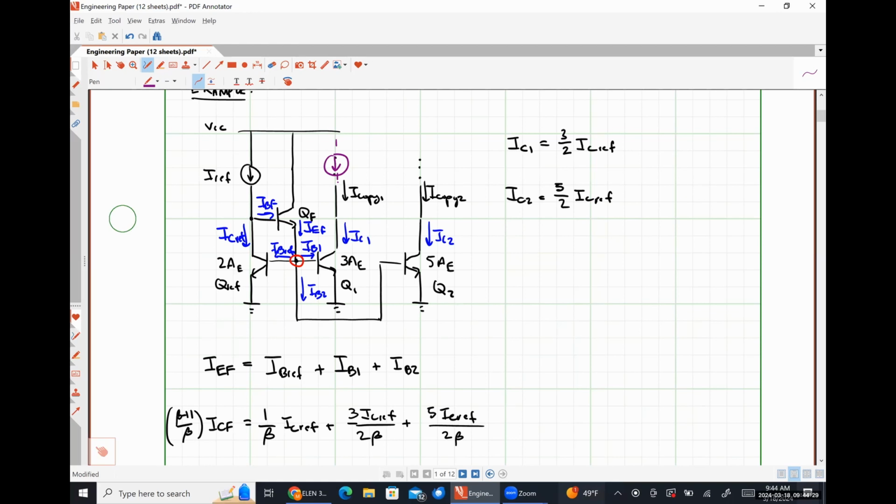So we are not relying on anything in particular here about one driving the other. We're doing all of our analysis just based on KCL, KVL, and effectively seeing what shakes out, with our ultimate goal being to figure out the relationship between any of these copy currents on the right-hand side and that reference current source on the left. By inspection, there's a base-emitter voltage between here and here, and that exact same base-emitter voltage must be here, because the bases are tied together and both of the emitters are on ground.